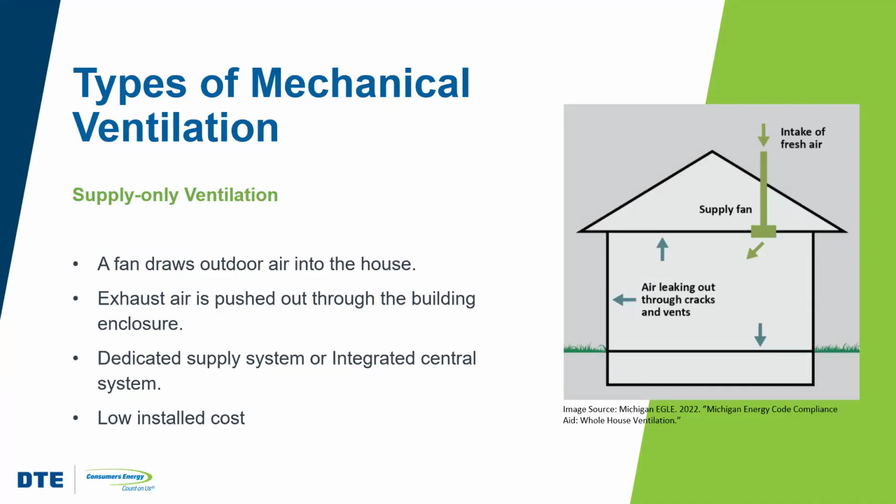And so you're able to bring that air in and then condition it that way, right? Or you may have a dedicated supply air system where you've got a filter and a tempering piece of equipment in that system directly. These systems are a little bit more involved, and so they cost a little bit more than the exhaust only systems.